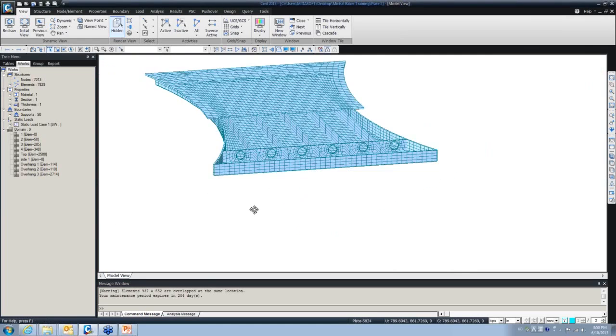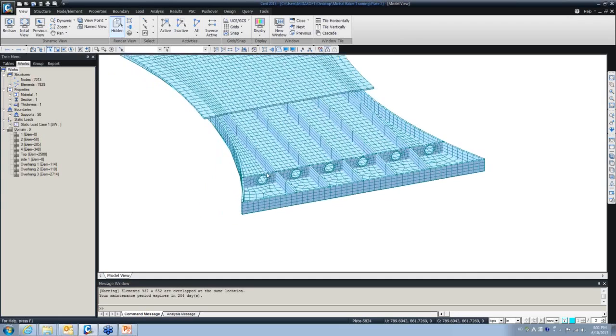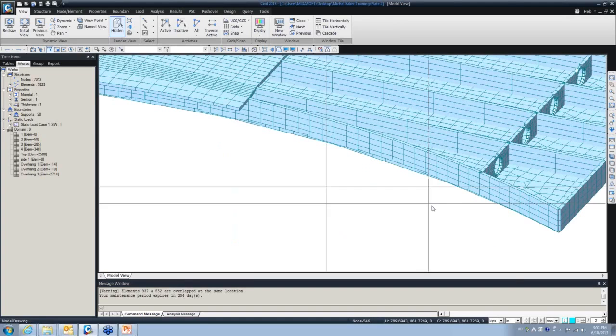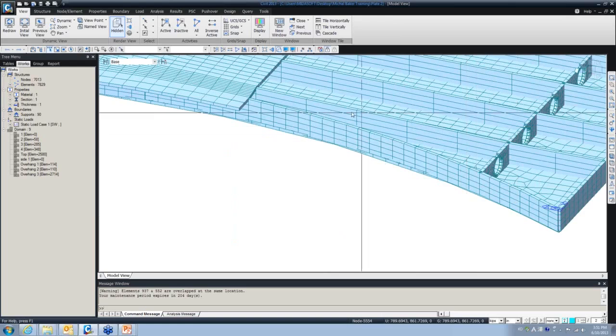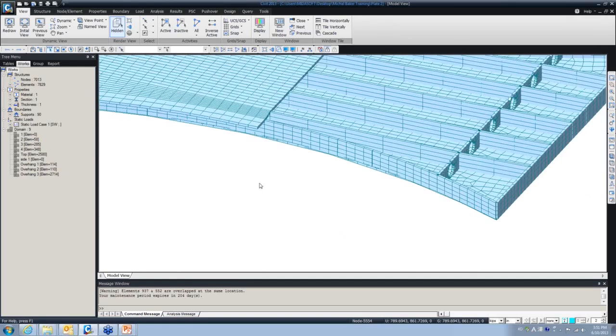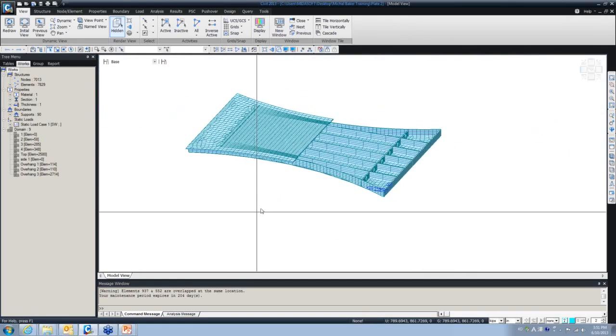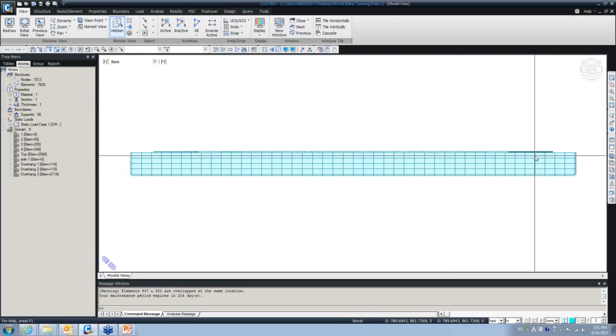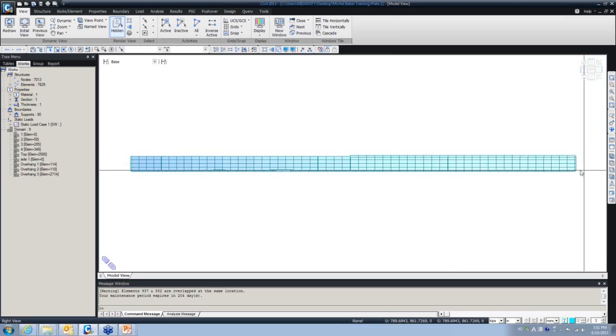So I'm going to show you what the workaround is. For example, if you have this plate and you want to post tension this element, you just define a beam in the middle of this slab right here. It could be on a curve or on a straight element, it doesn't matter. Then we can post tension that beam element. There should be some assumptions and simplifications to ensure that everything goes smoothly and comes up with the correct result that we are looking for.